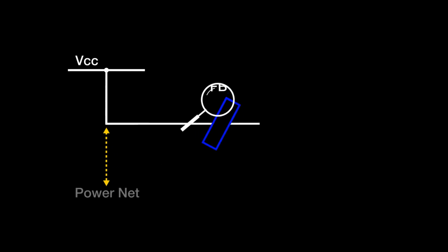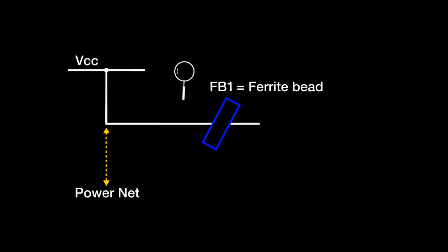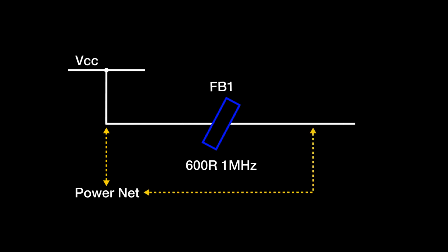XJ Developer will see if any of the power nets are connected to low resistance devices like ferrites, low value resistors, inductors or fuses. If they are, XJ Developer suggests that the nets on the other side of those components could also be power nets. It can do much of that using the net list, but to find low-value linking resistors, it will need BOM information, so it's important you've already imported component values.